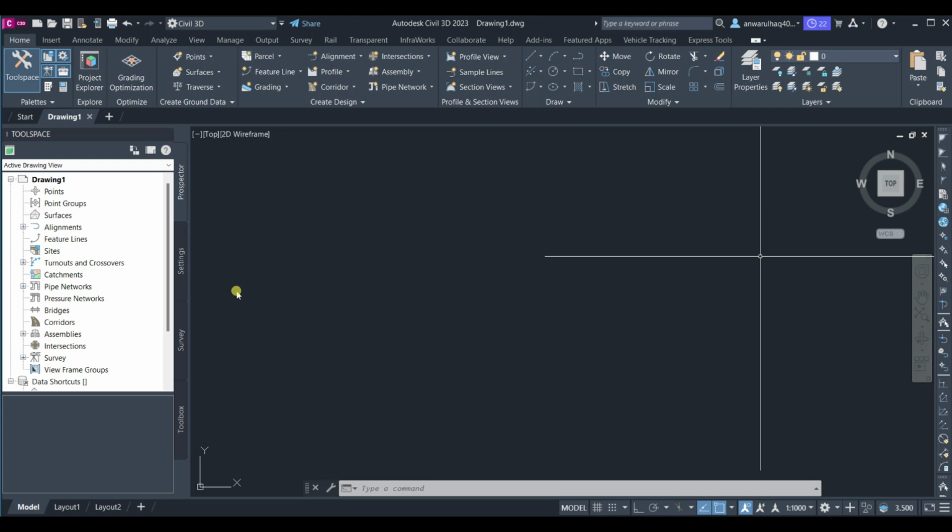So my suggestion is that you should go with proper projects. First you try to import points, because normally we import some survey points into Civil 3D. As an engineer or planner, you need to survey the land or whatever you are going to study in Civil 3D, so you should come with survey points or survey surfaces.